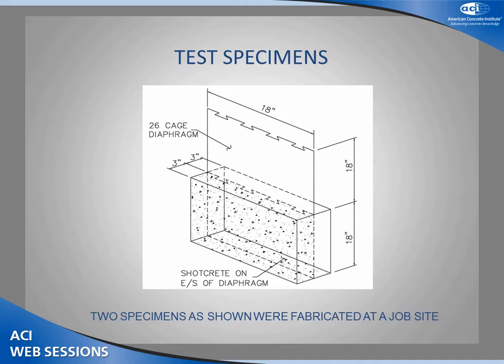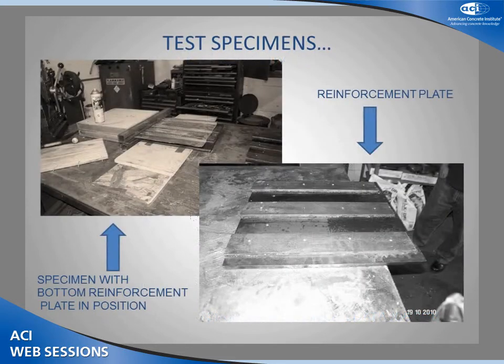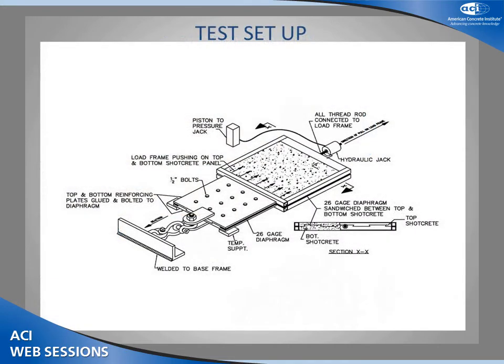So in order to ensure that, we had to stiffen this projecting portion of the diaphragm, and we fabricated special steel reinforcing plates, which we applied on the top and the bottom. We bolted it together and we glued it. So this steel plate is stiffening the entire diaphragm except at that interface where you have the load frame, and you'll see this load frame in the next slide, so that when you pull this sheet out, the failure is going to be due to interface action here.